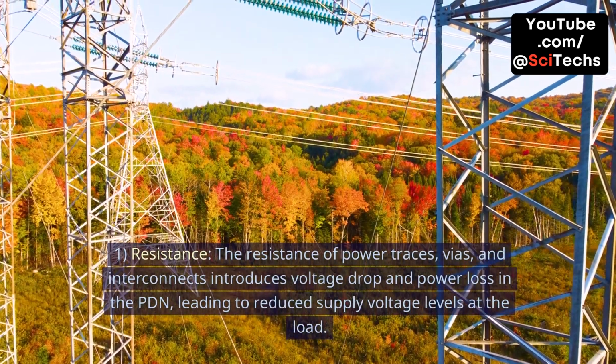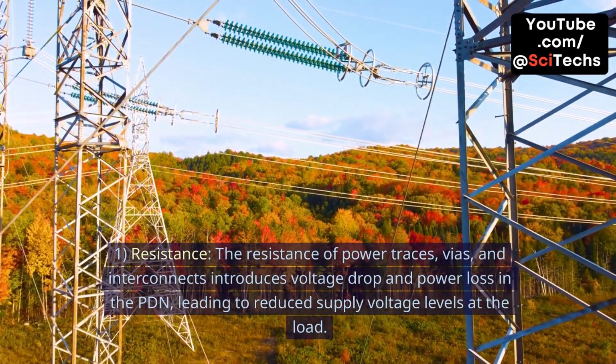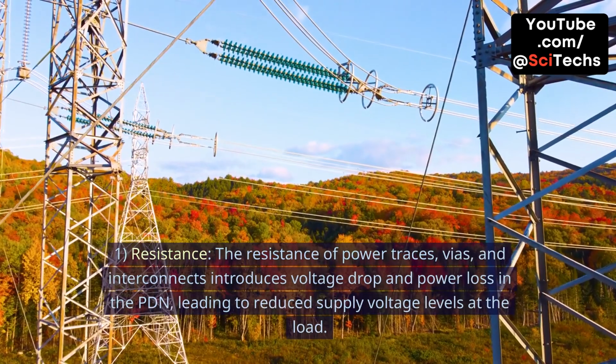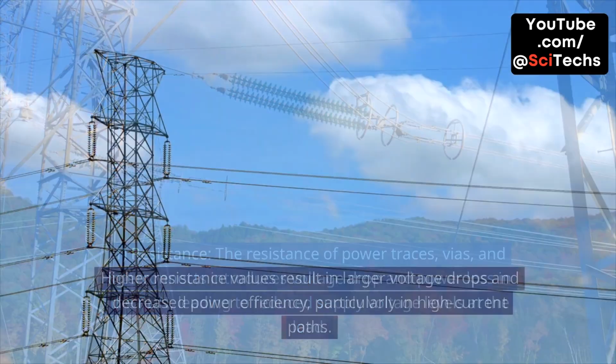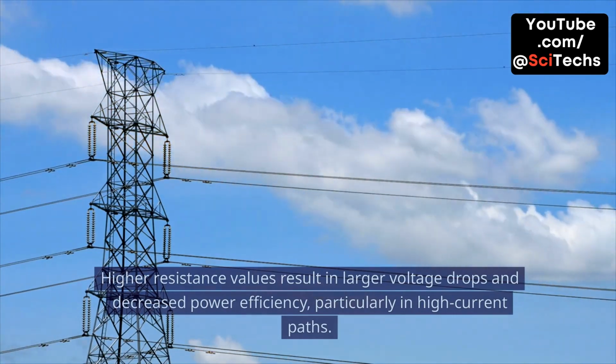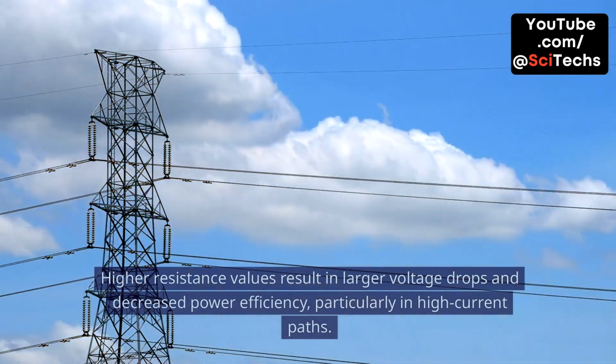1. Resistance. The resistance of power traces, vias, and interconnects introduces voltage drop and power loss in the PDN, leading to reduced supply voltage levels at the load. Higher resistance values result in larger voltage drops and decreased power efficiency, particularly in high current paths.